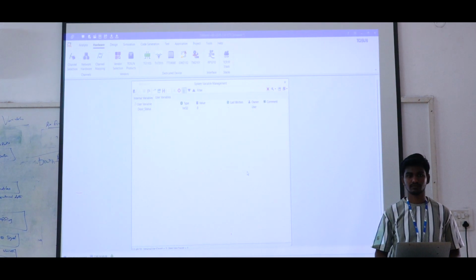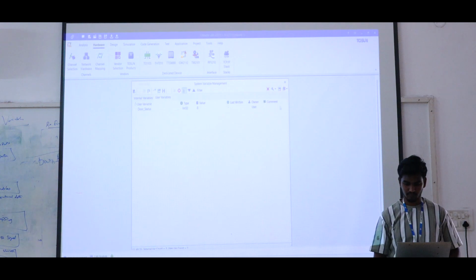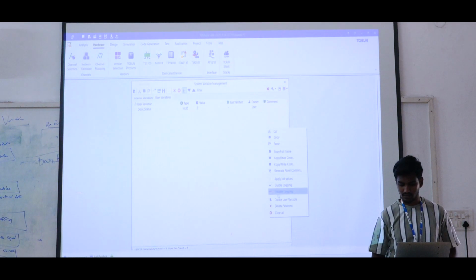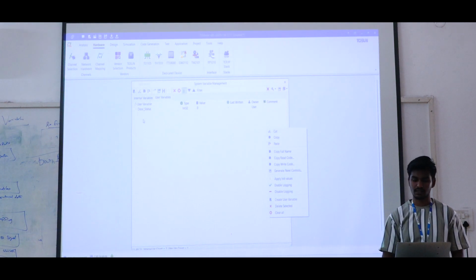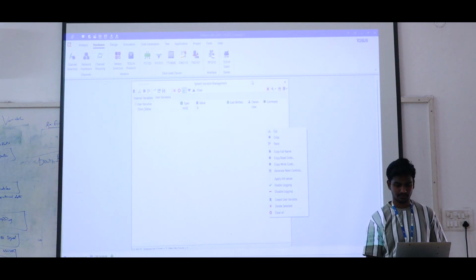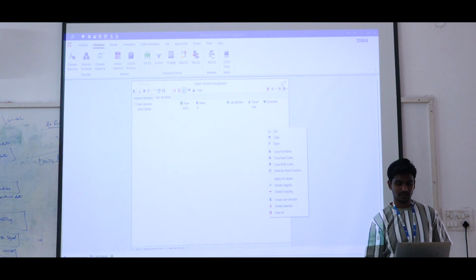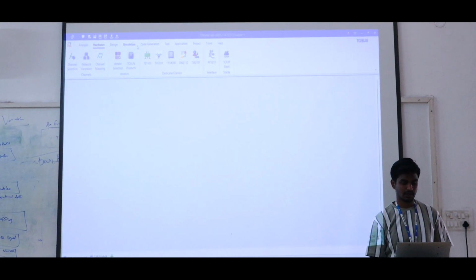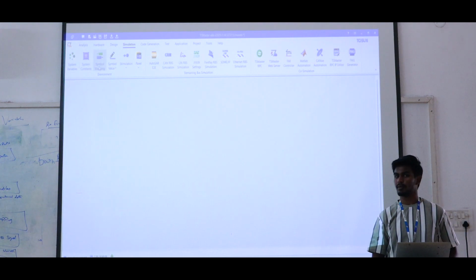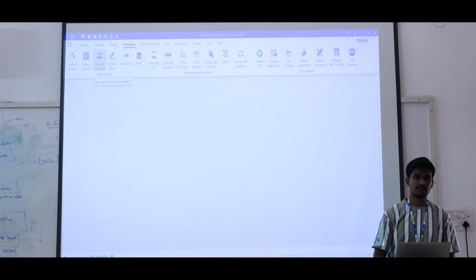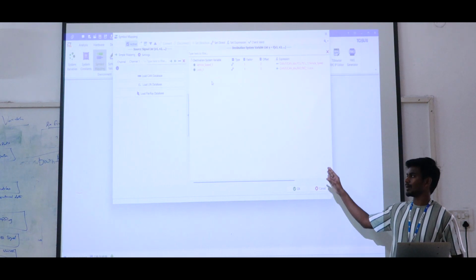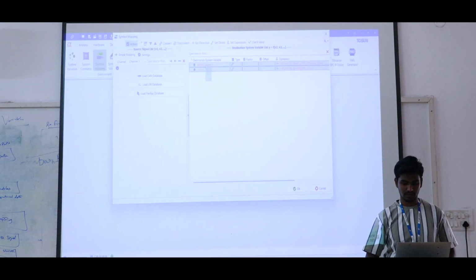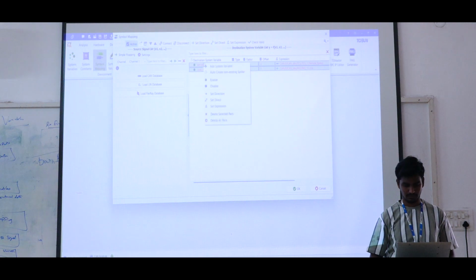Now create user variable. Right click, the create user variable option is there. You have to use that and then give the name as door status, minimum is 0, maximum is 1. So after creating this, you go to symbol mapping in our simulation. Open symbol mapping. So previously mapped variables are there. You just select them and delete them.